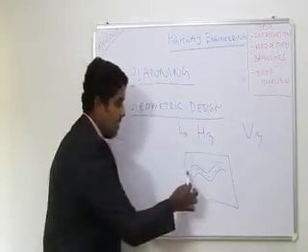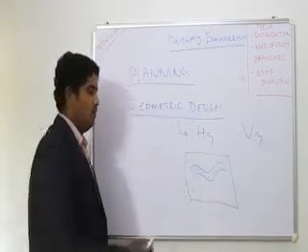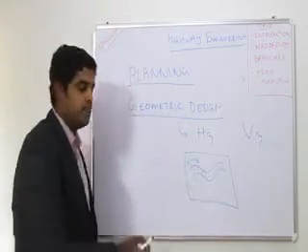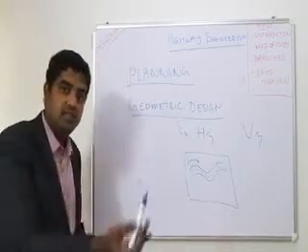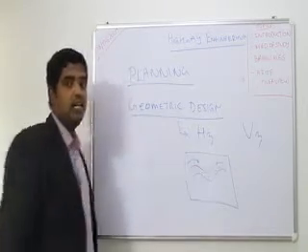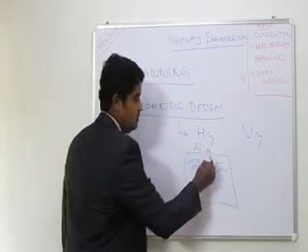How can you plan the alignment of the road? Is the radius of turning okay, how are the vehicles turning, is it correct, can people see other obstructions, is the road visible ahead, how much is sufficient? All of those come under the horizontal study, known as horizontal alignment.